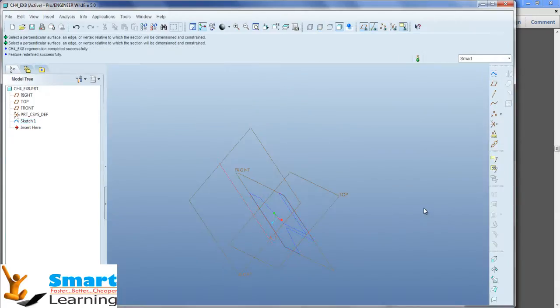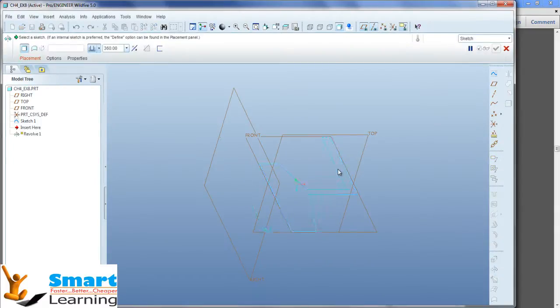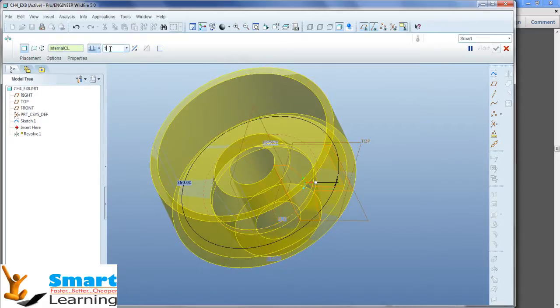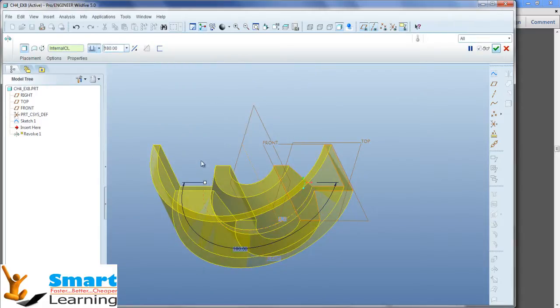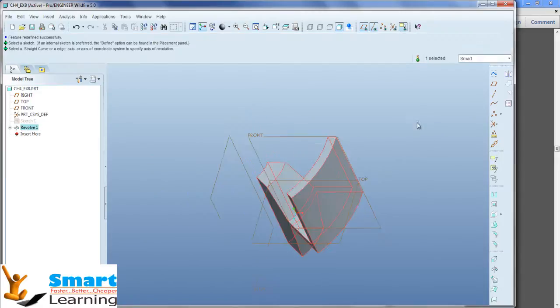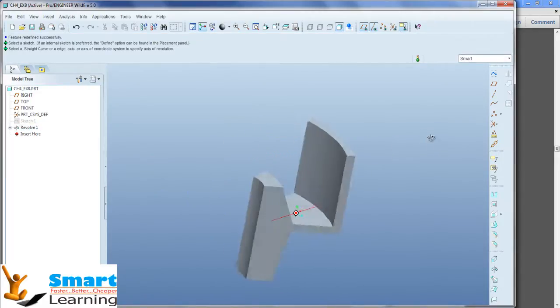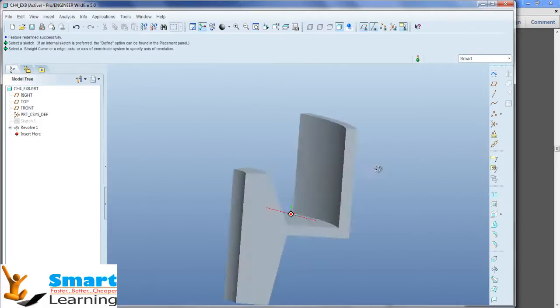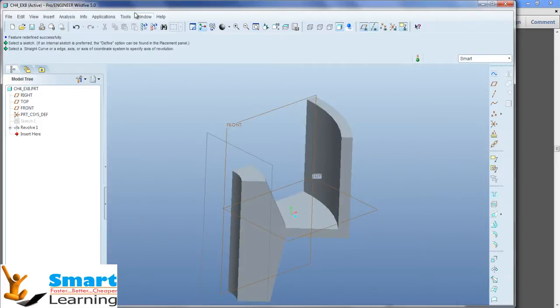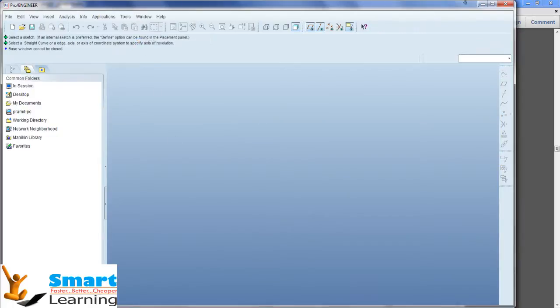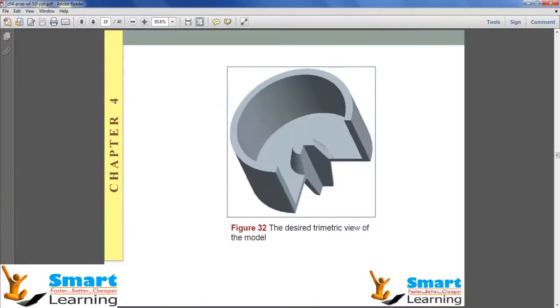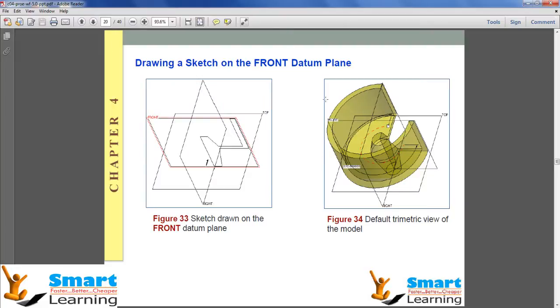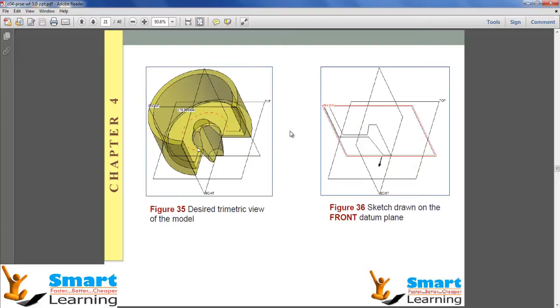OK it. Now this is front oriented, and when you apply the revolve and you apply, let us say, 180, from this particular location the 180 is started. This is our primary understanding which we are seeing in this particular problem. The revolve can be done from that particular plane with 0, 0. These are the cases. With respect to front, how you can control. With respect to right, how you can control.